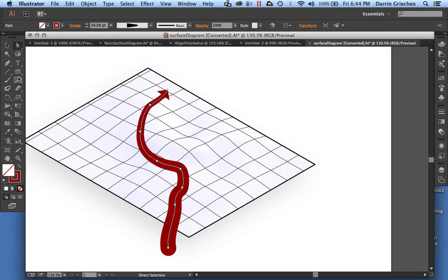Get rid of that little kink there by just erasing those two control points or anchors. So if I hold down the key, click, and go over here to delete anchor point, I can just come in here and say goodbye, and goodbye. Okay, that's a little bit better.